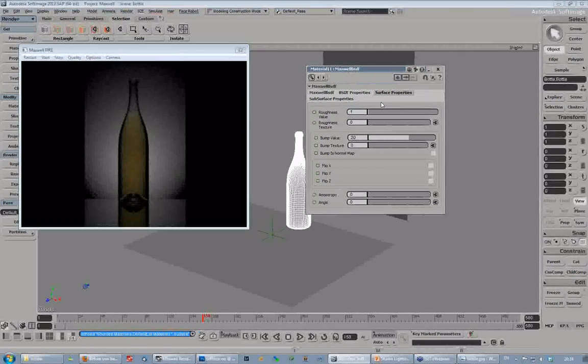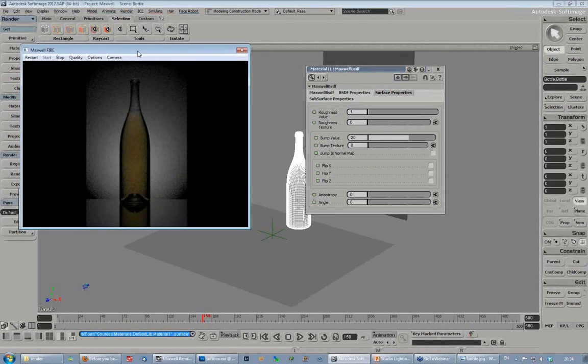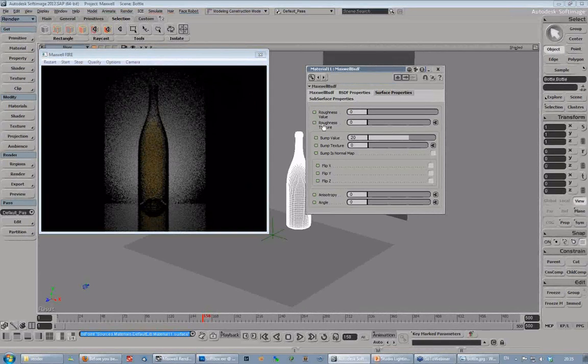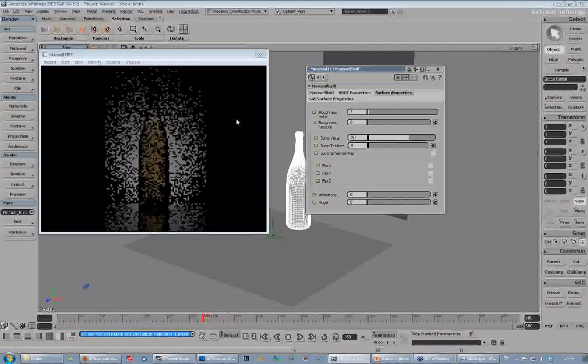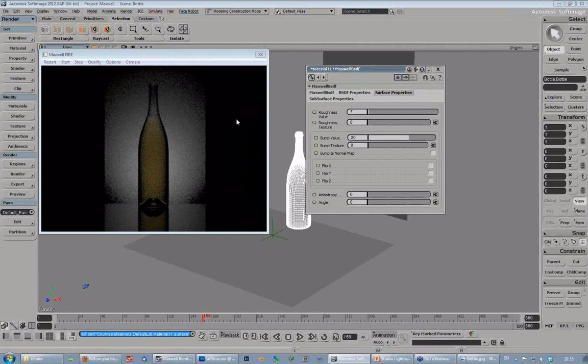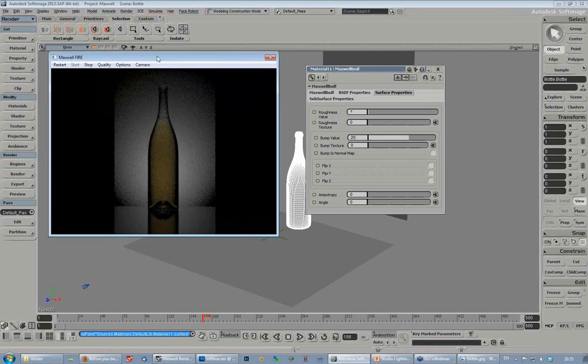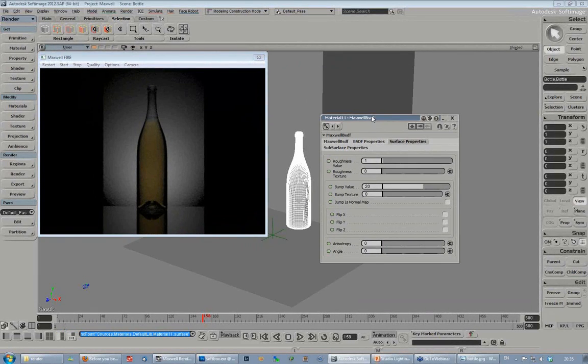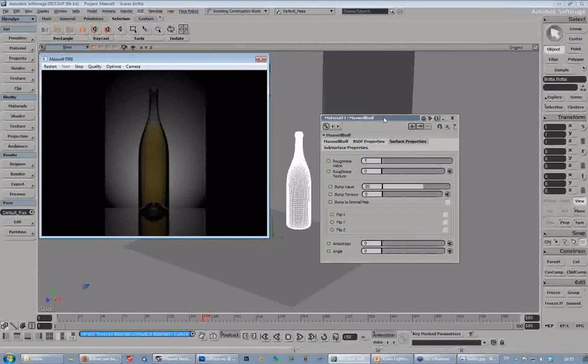And by the way, when you work with really specular materials, try to avoid setting the roughness to 0, because that means it's a perfectly smooth mirror surface, and those surfaces really don't exist in the real world. So always start at roughness 1, even for what would be a perfectly smooth mirror finish in the real world. Just adds that little bit more edge of realism.